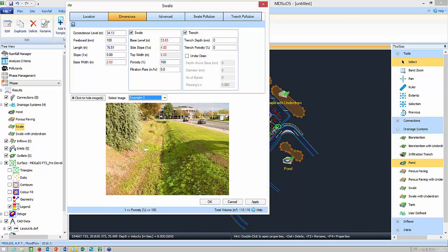And here's your typical example where runoff coming from the highway, ideally across the grassy strip, filter strip, to then get into the swale would be the ideal way to go with this one, rather than having gullies and what have you with point inflow. So this is a sort of ideal situation where you can have lateral flow coming in constantly as you go down along the highway.